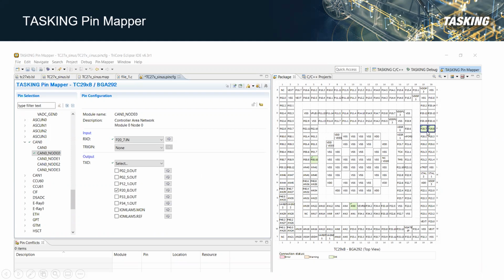Where you have 5, 6, 7, 8, 9, up to 15 different pins that are associated, and you want to cluster the pins in close proximity on the microcontroller for ease of layout.